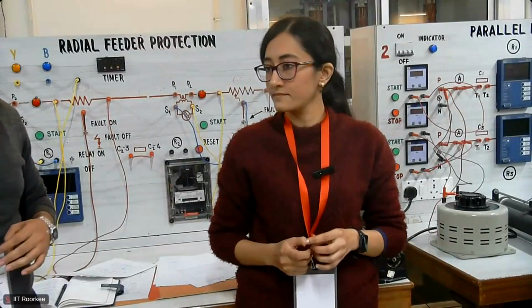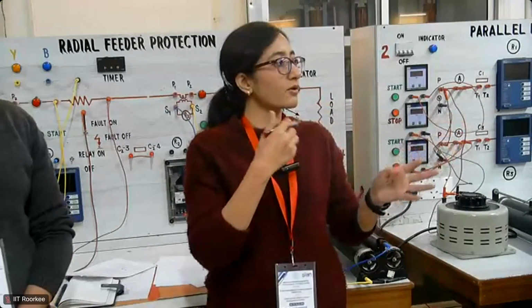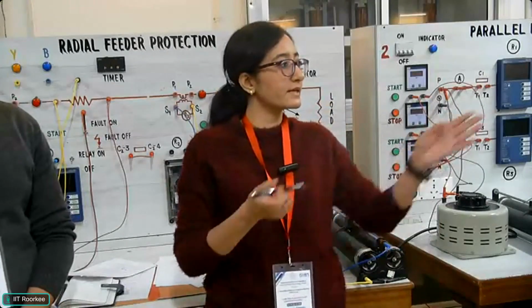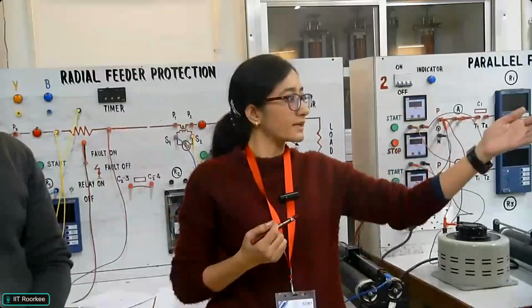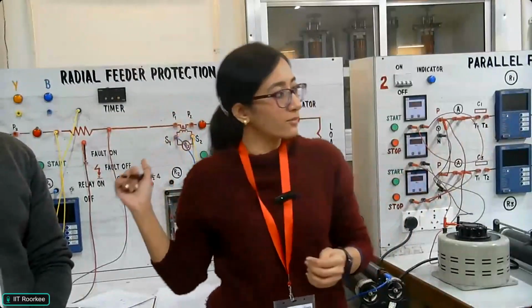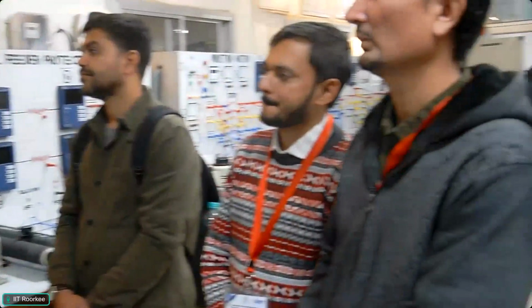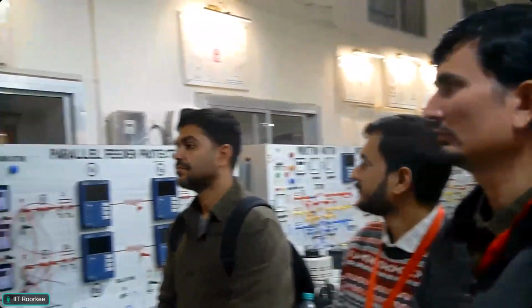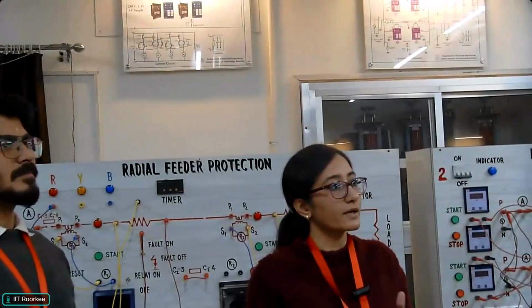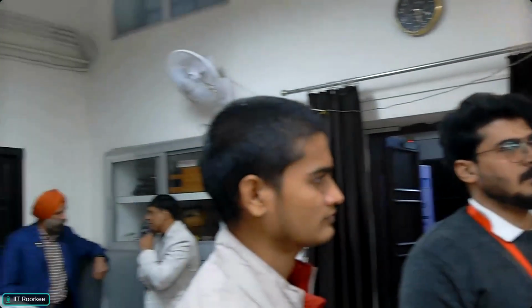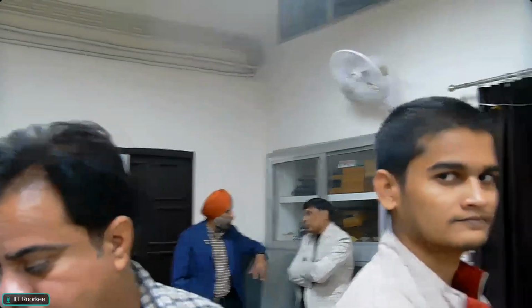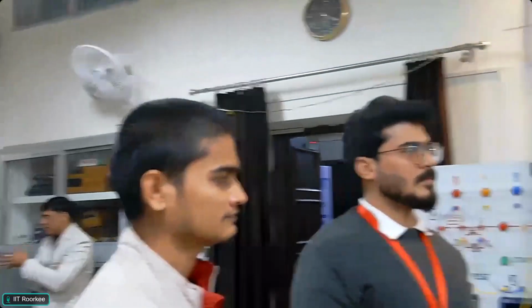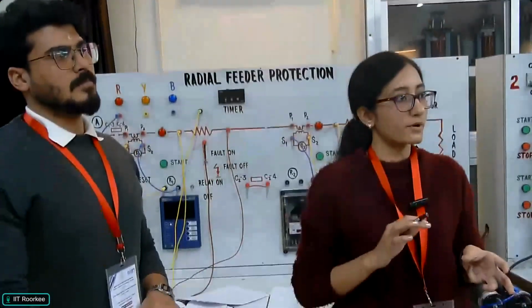Basically, in the laboratory, what we have designed is protection from a substation perspective. The generator you have already done, then the transmission line is there. Then from a distribution perspective, we have different configurations of feeders: a radial feeder configuration, and then a parallel feeder configuration or ring main configuration. These are the panels designed to first analyze protection, like how we design a protection scheme, then the role of digital relays or IEDs, how they sense faults, and how primary and backup protection work.